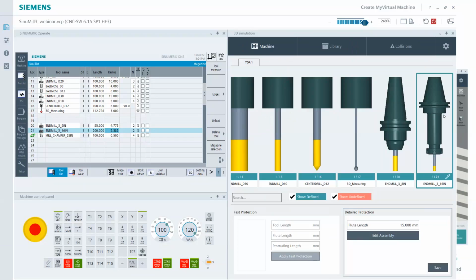This length is always from the spindle face to the tip of the tool, not necessarily just what the tool is inside of your holder. Right? You're used to grabbing an end mill off the rack. What's the overall length of the end mill? That length isn't just the end mill, it's the stack of all the components combined.